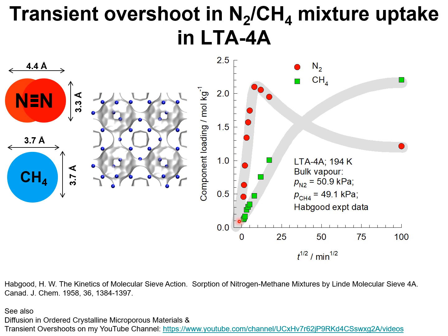So the technological solution is to resort to kinetic separations in which we rely on separating the binary mixture by relying on the higher diffusivity of nitrogen within the pores of LTA4A zeolite. Now, nitrogen is a pencil-like molecule whose cross-sectional dimension is 3.3 angstrom, that is significantly smaller than the diameter of the methane molecule.